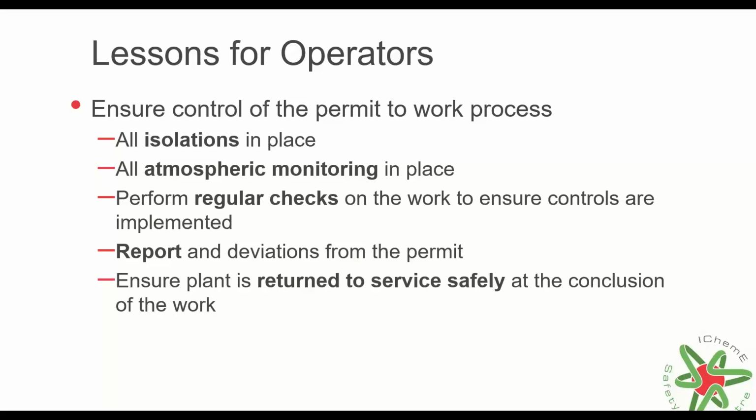And do I need to do it this way? Does it actually need to be hot work? If you need to cut into a line, could you cold cut that line with an air hacksaw rather than using an oxyacetylene torch potentially? Are there different ways that you can achieve the outcome you're looking for?